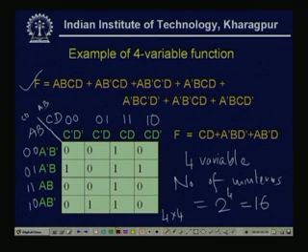First we see that there exists one quad here. This is one quad. Now, see here there is another couple and another couple. If I fold, I can put this and these as one couple. So, two couples and one quad exist in the 4 variable function given.